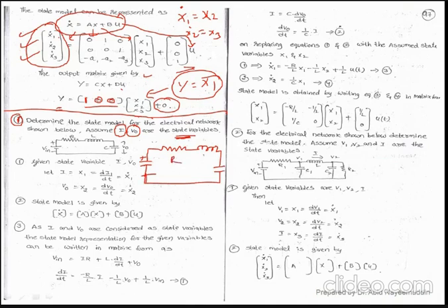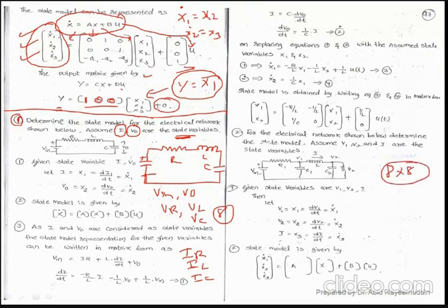So here R, L, C, how many variables in general? V in and then V naught, and then I can write the voltage across resistance, the voltage across inductance and the voltage of capacitors, and next the current flowing through resistance, the current flowing through inductor and the current flowing through capacitor. These are totally 8 variables. If you represent the state model with the 8 variables, you will get an 8 by 8 matrix. Hence in the examination he will give you the state variables.